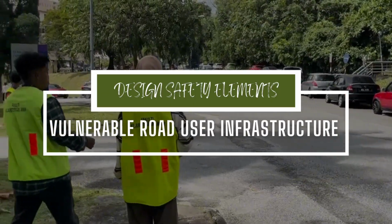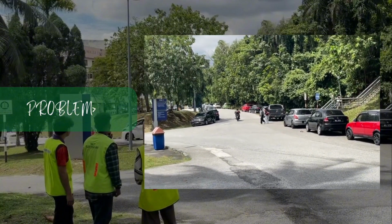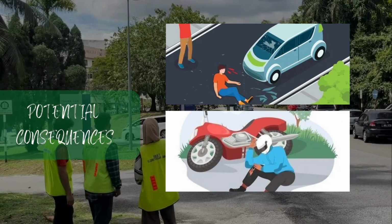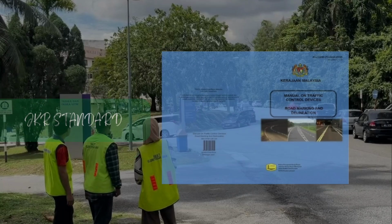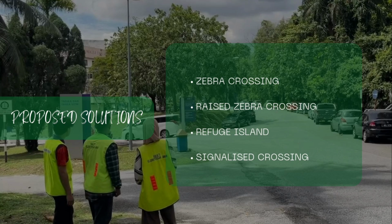Vulnerable road user infrastructure. The problem is there is no zebra crossing for the people to cross the road. Potential consequence, accidents by cars and motorcycles to the people crossing the road. For this problem, we can use JKR standard road marking and delineation. Proper solution, put a zebra crossing or raised zebra crossing, refuge island or signalized crossing.